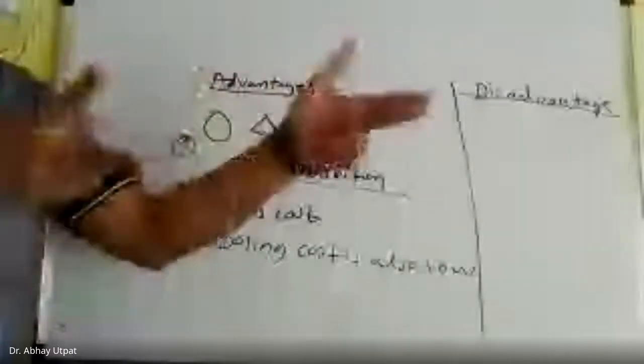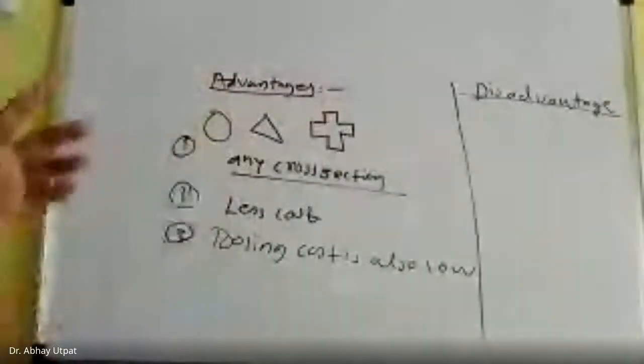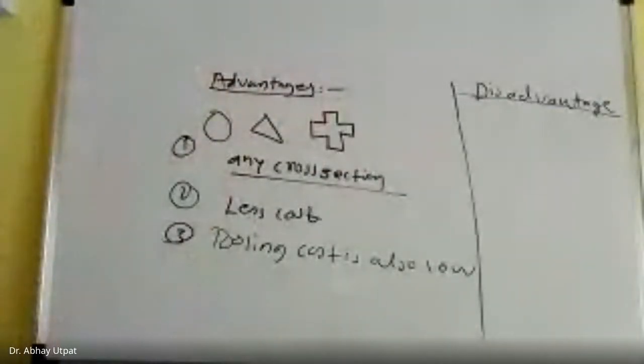Almost 40 to 50 feet distance is kept, and throughout that length the water sprinkles are on the pipe. If that cooling is not provided, there will be distortion of the pipe, and then it is cut in between and thrown away. That's why cooling plays an important role in the total cycle time of plastic manufacturing.